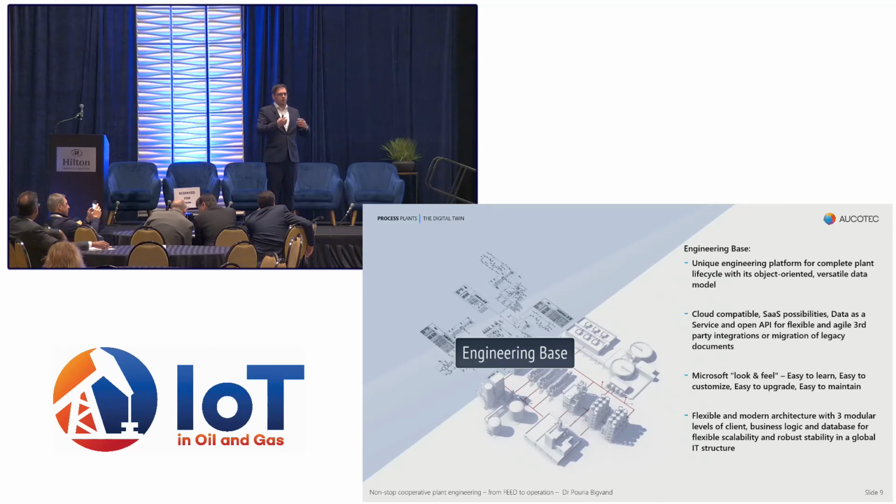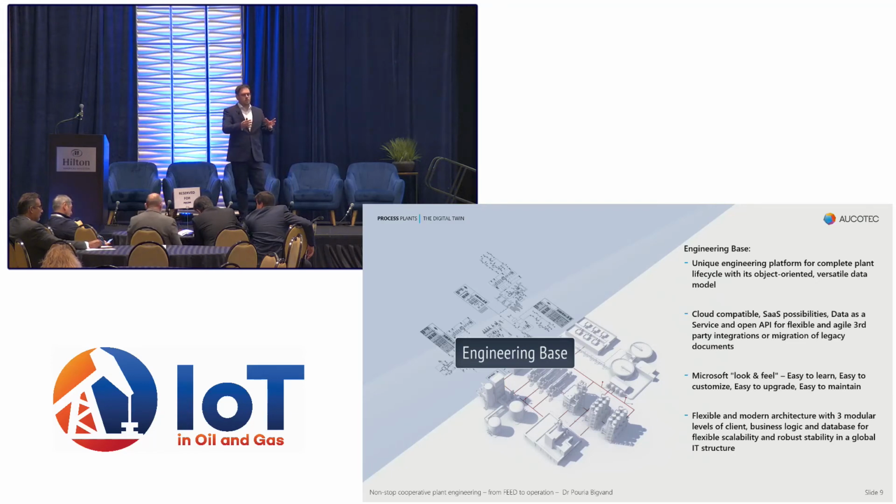So when there is a P&ID guy sitting in front of a computer, he designs a P&ID. The system will recognize that there is a tank which is connected to a pipe, and this pipe has different inline devices, and each of these inline devices is connected to a wire. And this is what the user is doing. He's graphically designing, and behind the scene, the data model is generated. And of course, this data model is used later for all kinds of reports and any kind of accessibility of data to other tools like predictive maintenance and other activities for data usage.